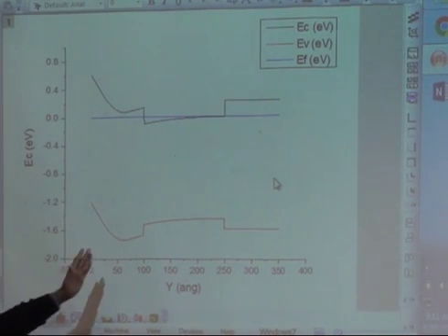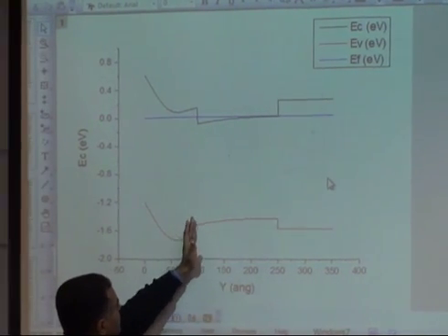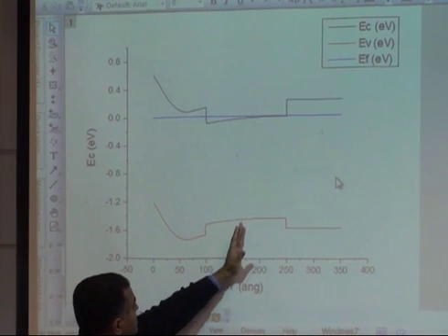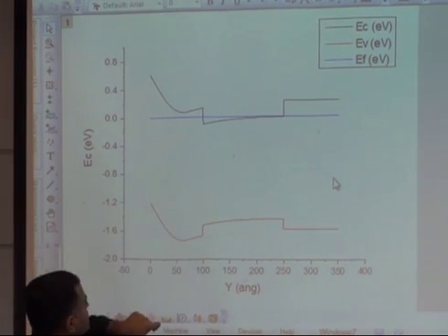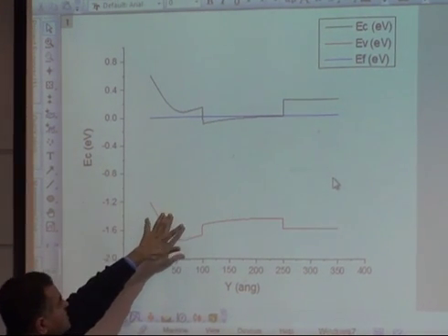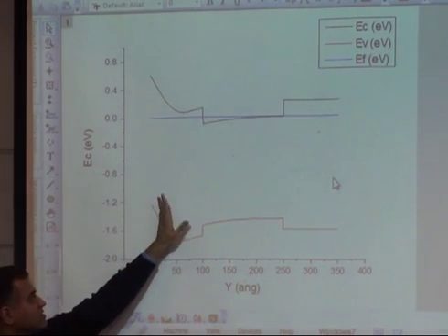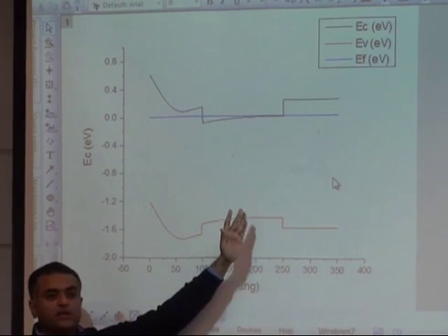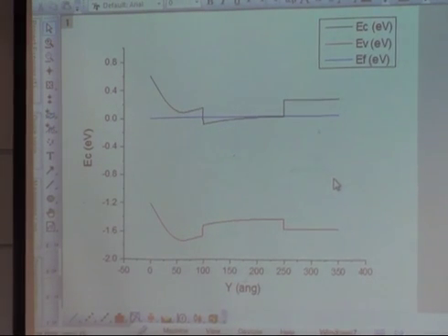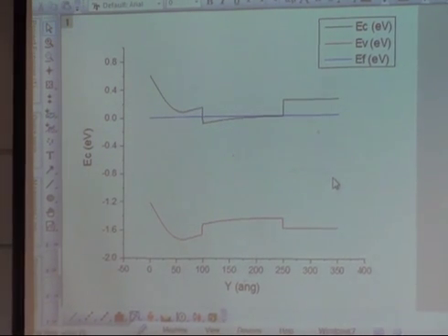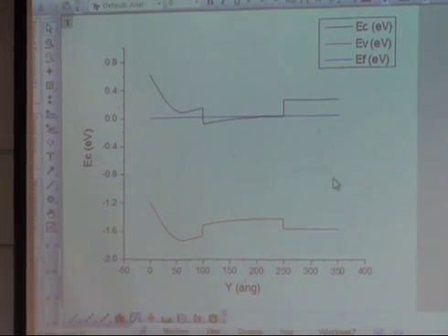So yeah, basically, if you integrate the mobile electrons in the conduction band, here you got 2E12. The ionized dopant density is 1E13, but the whole thing must be charge neutral, right? So I have 1E13 positive charges here, 2E12 negative charges here. Where are the rest of the negative charges? So barrier meaning where? So meaning here into this.